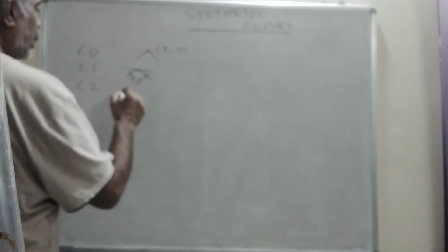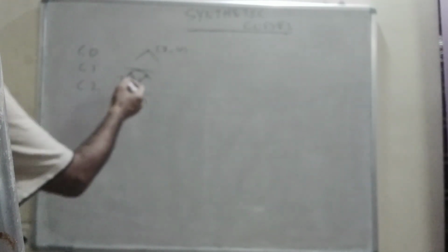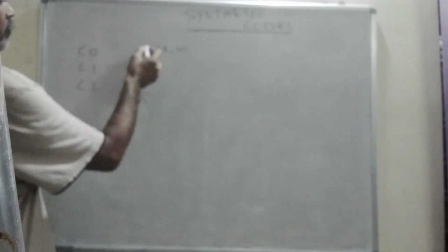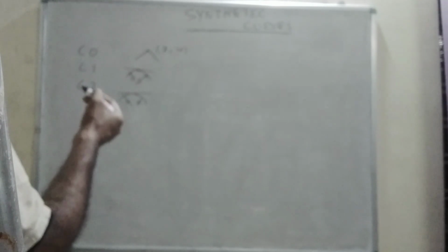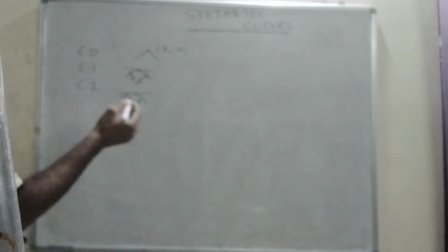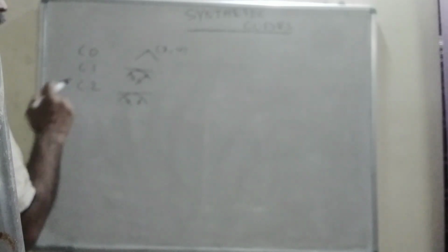So this is C1 continuity, and C2 continuity is where two curves meet at a point, they share a tangent, and both curves have the same radius of curvature. So here, two different radii of curvature, and these two points will have infinite radius of curvature. That is how a curve should have C0, C1, or C2 continuity. Normally, from cubic order onwards, we have C2 continuity of curvature.